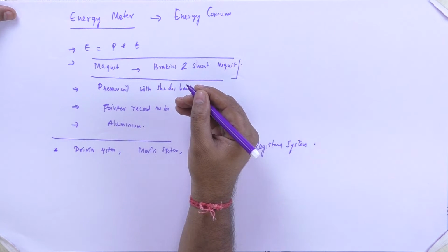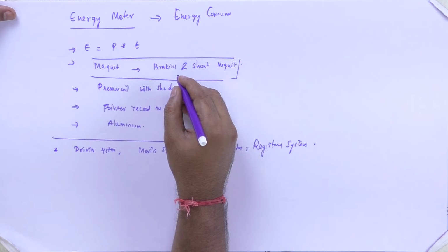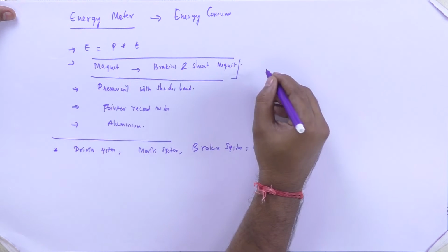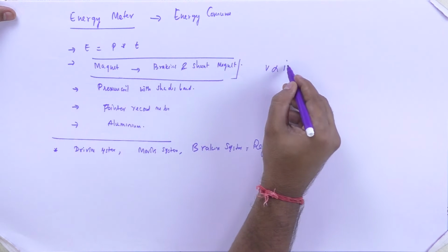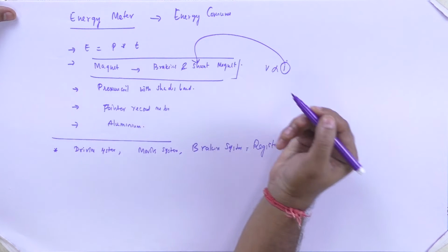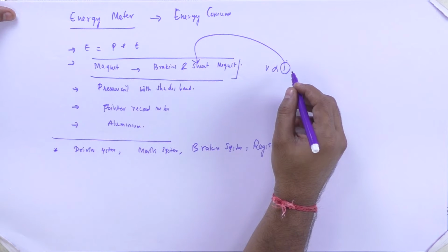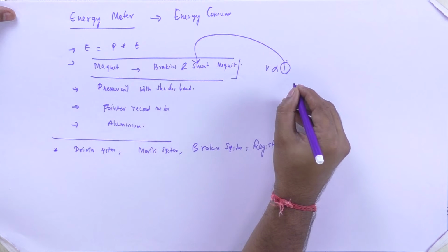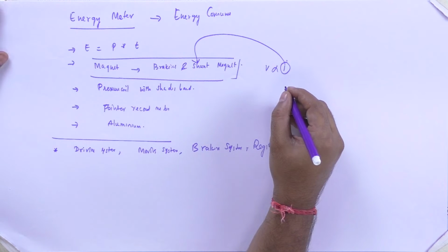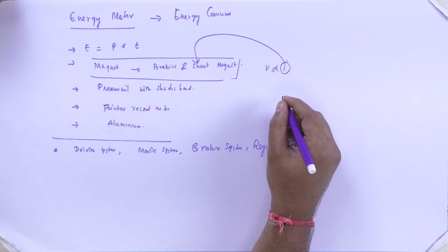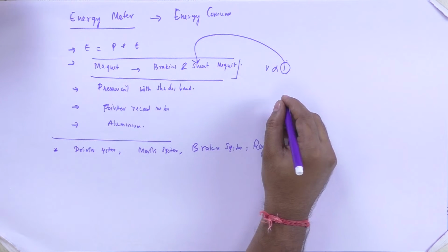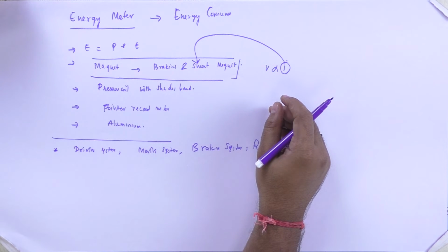The upper magnet is connected to the coil called a pressure coil. The coil in the shunt magnet is directly connected to the supply, and it carries current proportional to the voltage. So the applied voltage is proportional to this current, and this current is carried by the shunt magnet on the upper side, connected to the coil called the pressure coil, as I discussed earlier. The center limb of the magnet has two important copper shading bands, and these bands are adjustable.